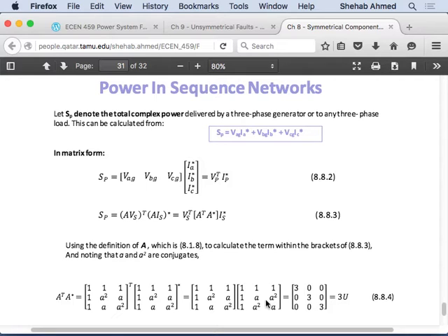You don't need to memorize it, but once you do it a few times and you understand, okay, star, if there is a neutral impedance, zero sequence current will flow on the primary. Is it going to flow on the secondary or not? You look at the secondary side. If you reason through it, you will not need to look at it, but it's included there. So basically, what we're going to do next is show you a system and build the sequence circuits for this system. And then what do we do with them? That's what we're going to do also in the next chapter.